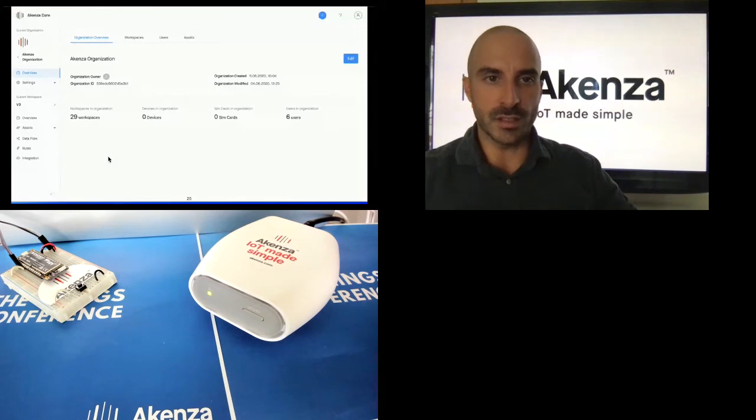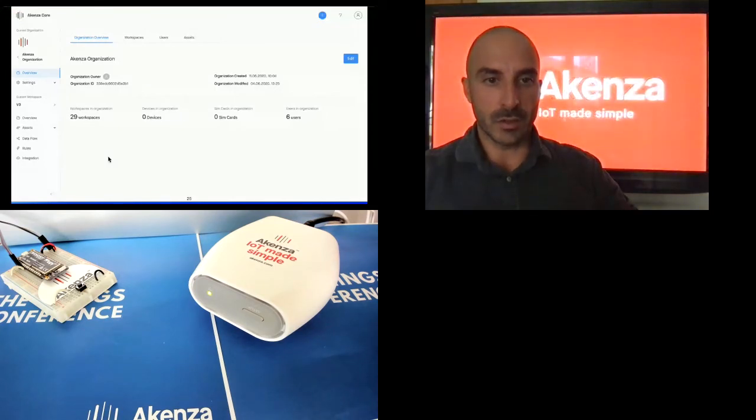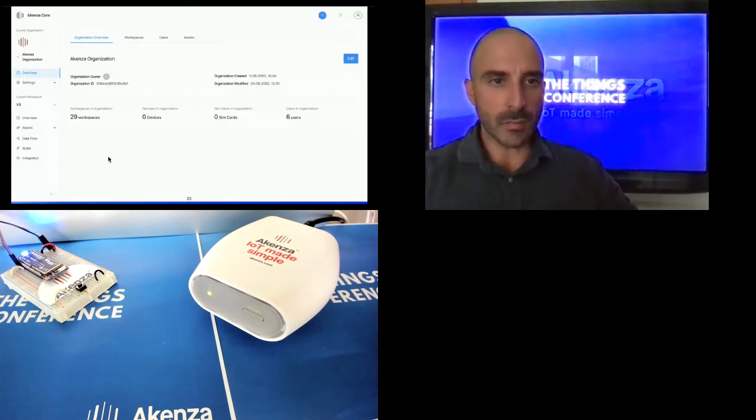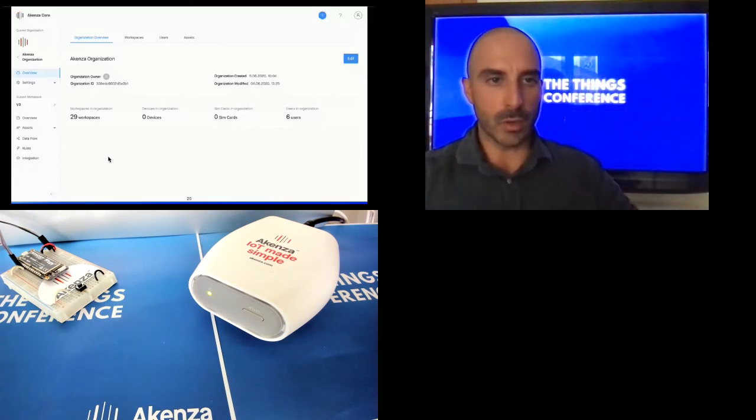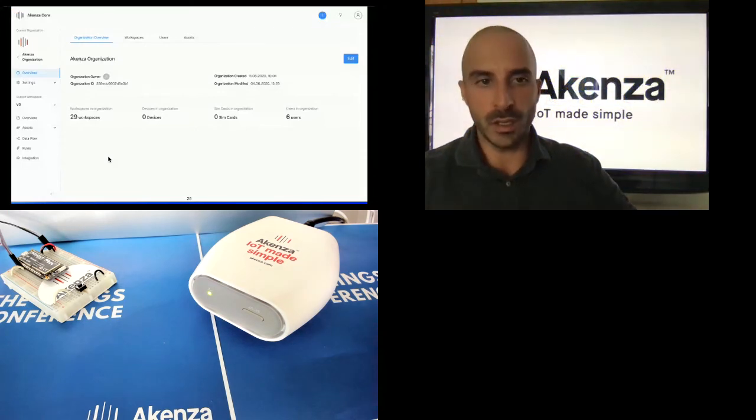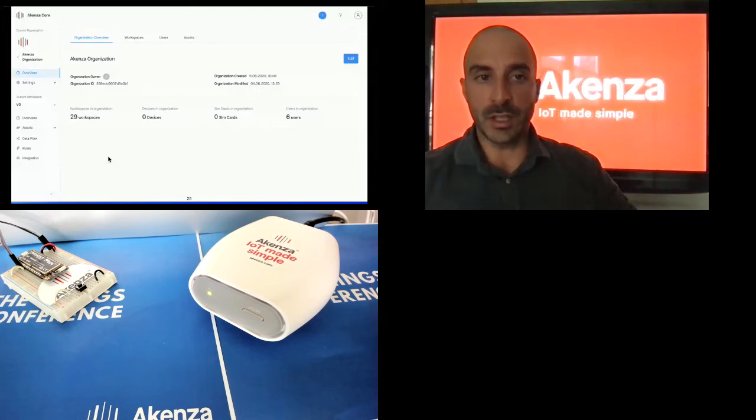You already see that it's quite different from the current one. You just have to choose TTN integration, select what the LoRaWAN host is, and the authentication method. You just insert the user ID as we have chosen user ID. And that's it.